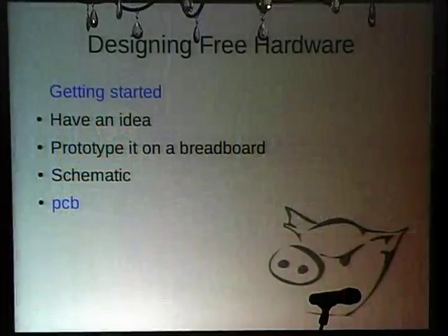Right. If you're waiting till the PCB design stage for that kind of troubleshooting, you're going to have nothing but headaches, because then you've got to move whole components around and reroute traces. Right. And so when you do the schematic, you go through every data sheet, check all the specs, and make sure everything is within spec. And then once you've completed this, the next step is you're going to go into PCB. Then you're going to actually create a physical path for everything. Everything has to have a layout.